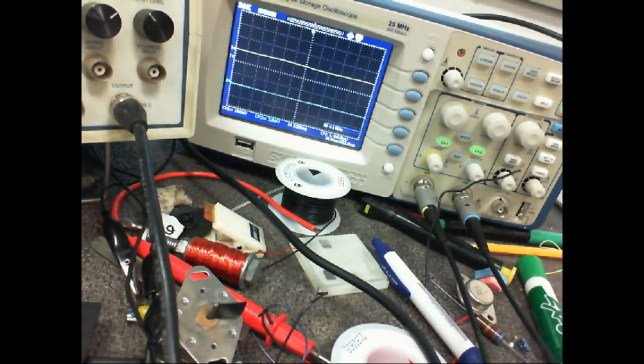With these, we've got to do something. We've got to do special things, right? It limits the distance it can run. It limits how we can run them. You never run signal wires in parallel with power wires, not unless you separate them by a great distance, right? Understand? So this is why, if you look at a power line, the power lines are up here and the cable TV lines are down there, about 12, 15 feet. You understand? So it gets out of the range of the electromagnetic interference.